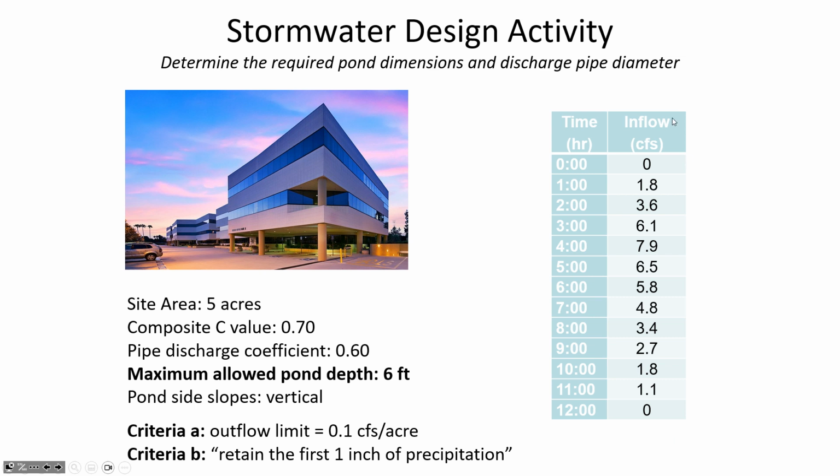So here's our inflow hydrograph. Let's just say that that's a given. In reality, you generate this as well. And how would you generate the inflow hydrograph? Well, you'd maybe put together a watershed model, just like something such as WMS can give you a runoff hydrograph.